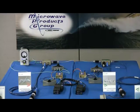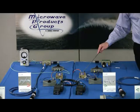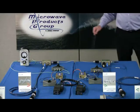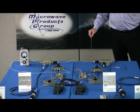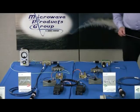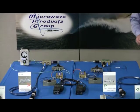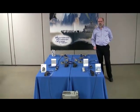The radios used in the relay have their audio signals coupled through this cable. Their antennas are coupled through two 20 dB attenuators in cascade to simulate the 40 dB between the UAV's radio relay antennas. It is this coupling of high-level transmit energy that degrades the sensitivity of the uplink receiver, creating Cosite interference.